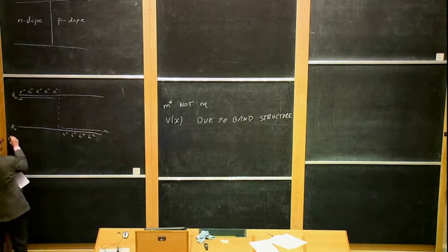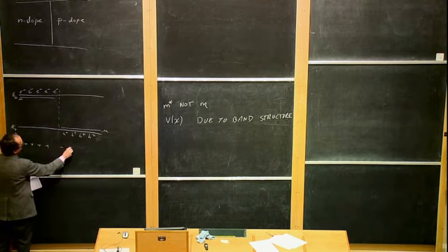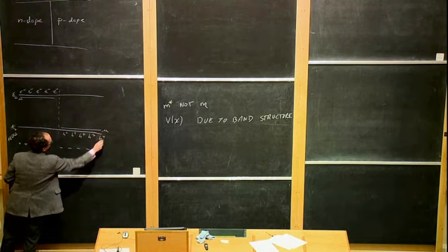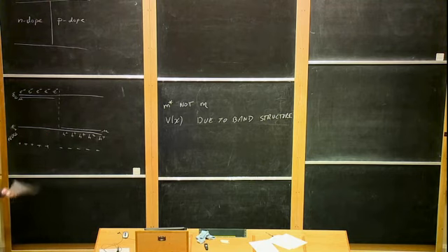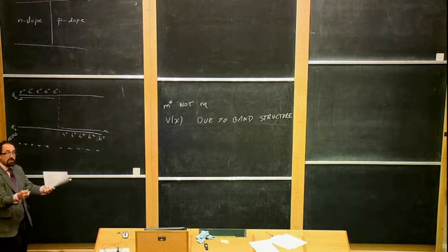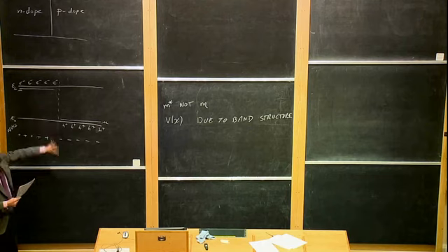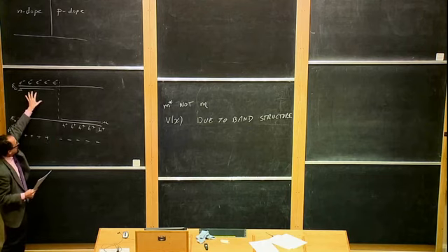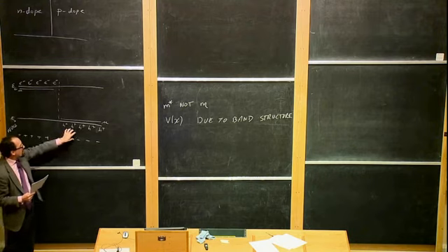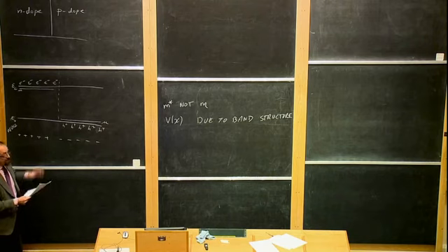So the nuclei have charges also, and they have compensating charges like this and compensating charges over here. Because you remember, when you add for example a phosphorus to silicon, you add an extra nuclear charge. You also add an extra electron. The whole thing is neutral. The electron goes off into the conduction band, but you left a positive nuclear charge behind as well. So everything here is electrically neutral, no electric fields. The electron negative charge is compensated by the nuclear positive charge, and the whole positive charge is compensated by the acceptor negative charge here. So far, so good.